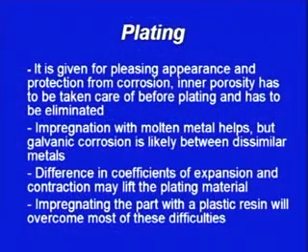Now, we come on to plating. Why is plating required? In the first lecture I also told that surface finish, or the characteristics of the surface, or the packaging of the component is very important. So, in order to improve the surface finish, or to give certain important characteristics to the surface, we go for the process of plating. Now, plating is given for pleasing appearance and protection from corrosion.